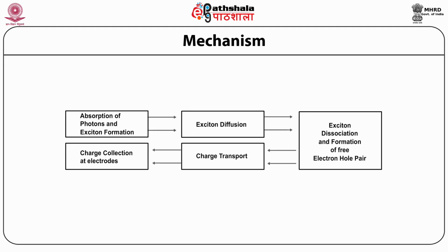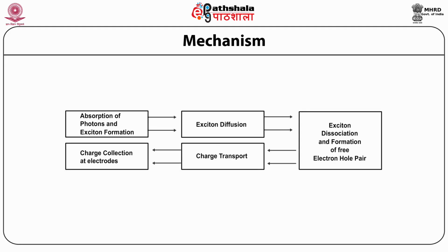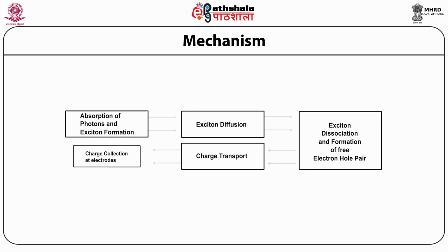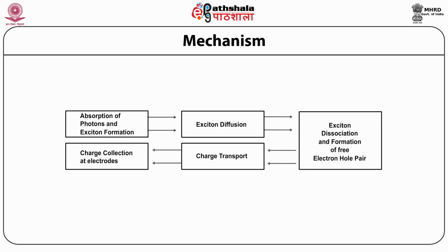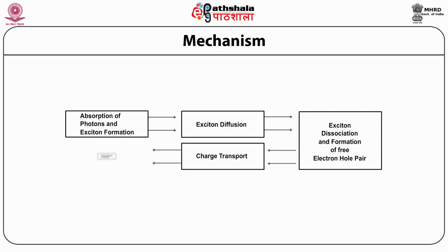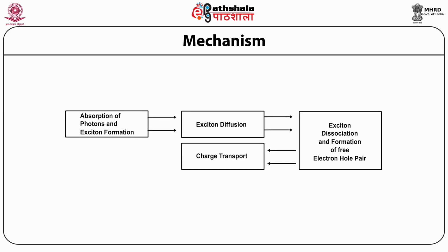The range of absorbed photon energies is determined by the absorption spectrum of these molecules. Each absorbed photon causes an electron to be excited from the HOMO level to the LUMO level and thereby leads to the creation of an exciton. The exciton formed is electrically neutral and its transport is not affected by the internal electric fields.